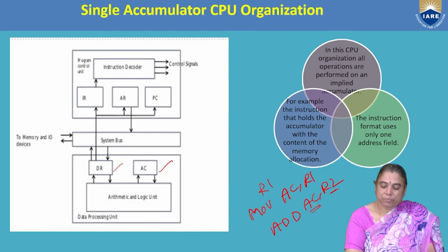Again, the sum is stored in the accumulator only. In this type of architecture, the assembly language instructions use the accumulator as one operand during arithmetic instruction processing.